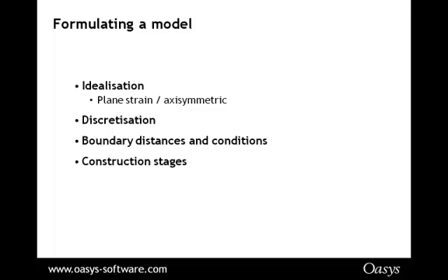You've also got the discretisation, which is really how the mesh is generated. SAFE now has special features such as auto-meshing, where you can, and also generally you can import DXFs to make a mesh. So we've tried generally to make the meshing process as easy as possible for the user to do.